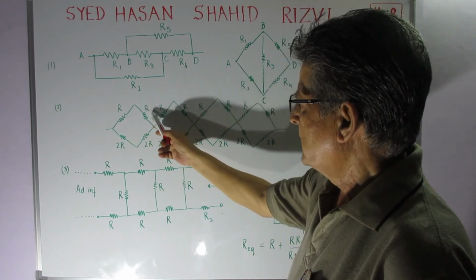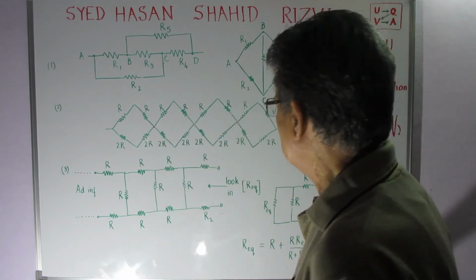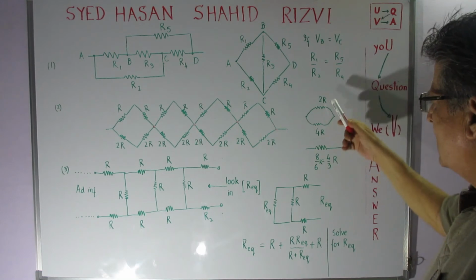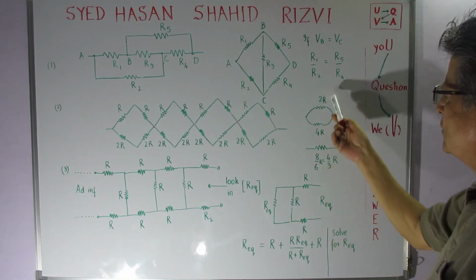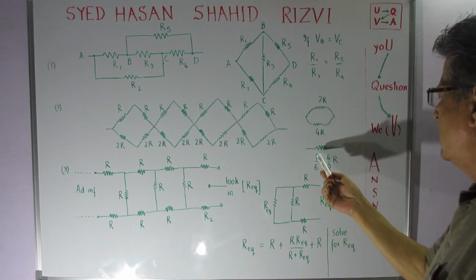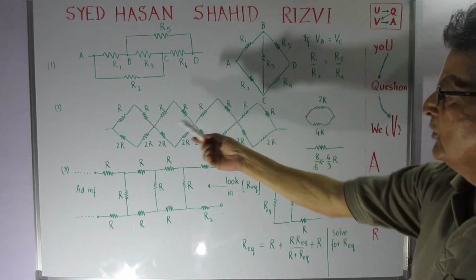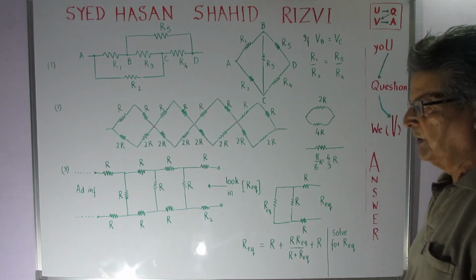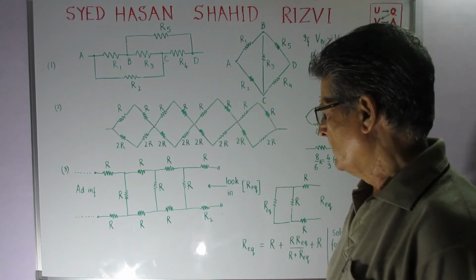Now the resistance R plus R is equal to 2R over here, and 2R plus 2R is equal to 4R over here, which I have shown as 2R and 4R, and then the net resistance will be equal to 2R into 4R divided by 2R plus 4R, which is 8 upon 6R, which is 4 by 3R, multiplied by 4, and you get readily the value to be 16R by 3. R can be given any numerical values also, there is no problem.